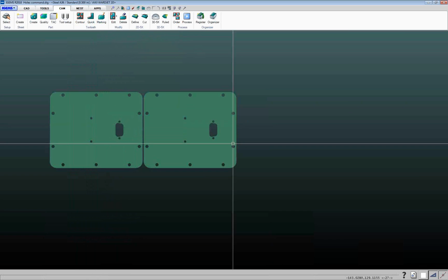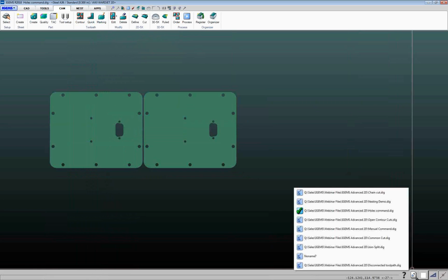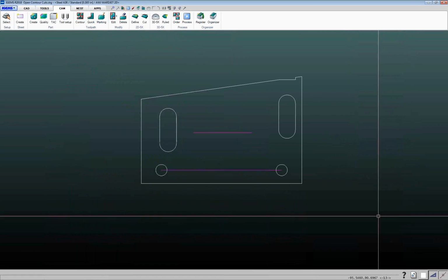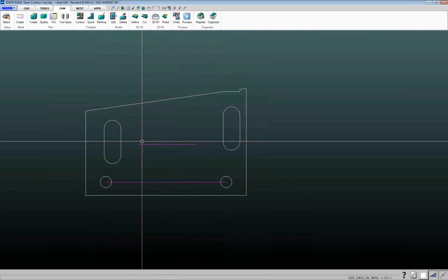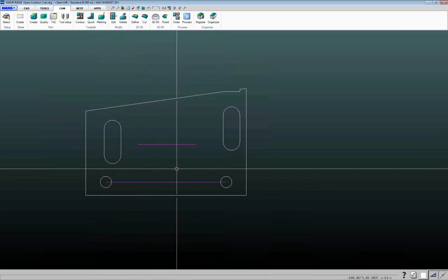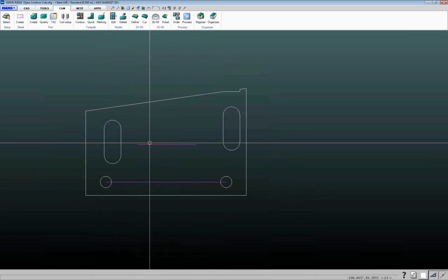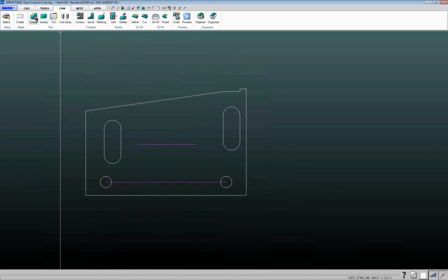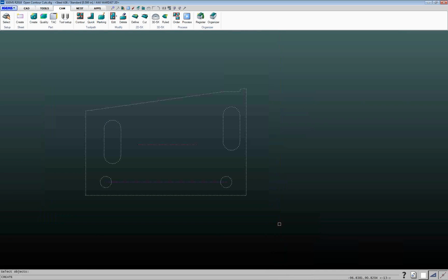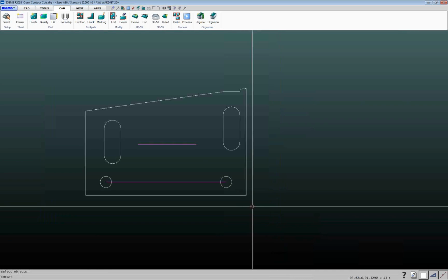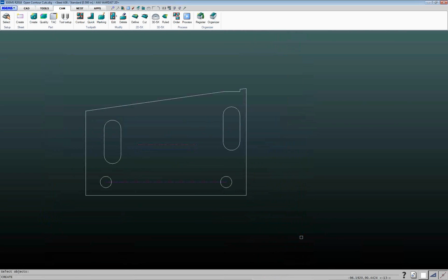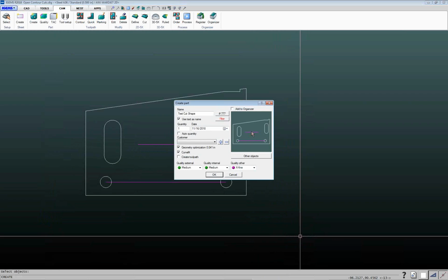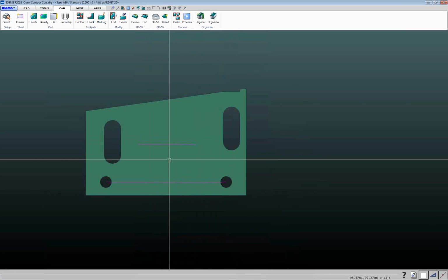All right, then next we'll review the open contour cuts command. So oftentimes we'll get one where people want to either cut or mark open contours on a part. So these lines here are what we consider open contours because the endpoints don't match up. So if you want to cut or mark things like that, when you create your part, click on this Other Objects button and then select those entities. They'll show up here in the preview with the magenta lines, and then you can add toolpaths to those things.